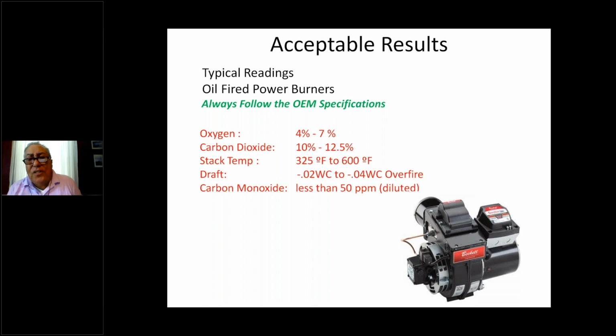Yes, you've got great efficiency, but if the air changes the slightest bit, from a little cat hair on those air gates, a little dust, a little lint, you have just gone over the edge. Now you're making soot, and that will happen quite rapidly. So my suggestion has always been not to adjust too high. Keep CO2 under 12%. 10 to 11% is really good.